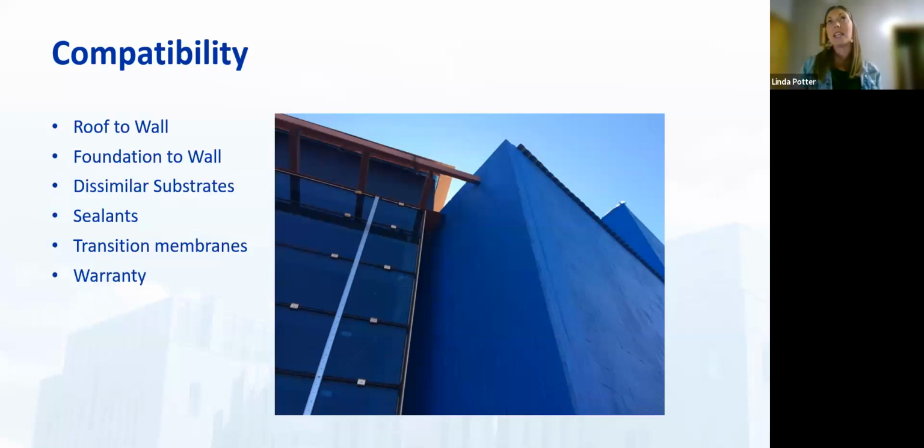The problem is that even if it's a single manufacturer doing all 6 sides, you're still having different chemistries and materials that function below grade versus above grade versus roofs or below slabs.